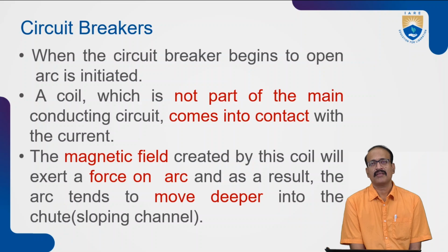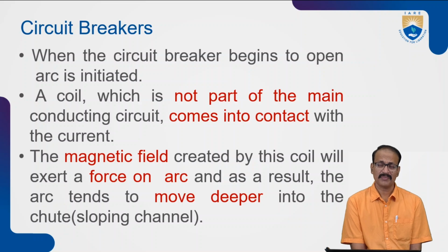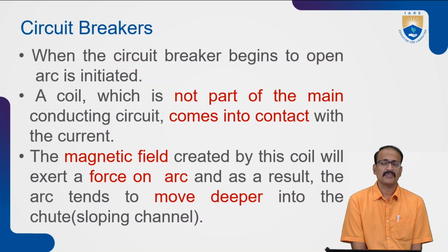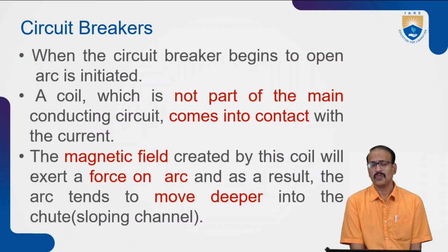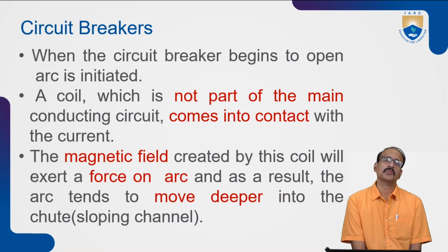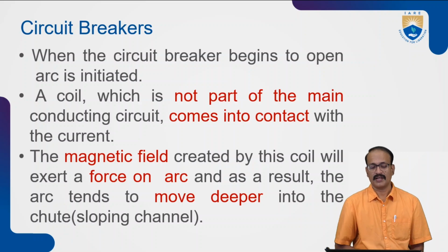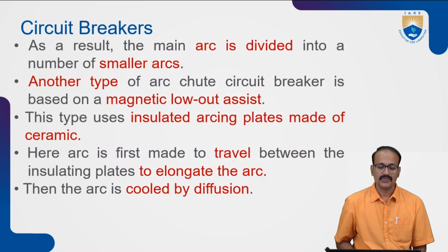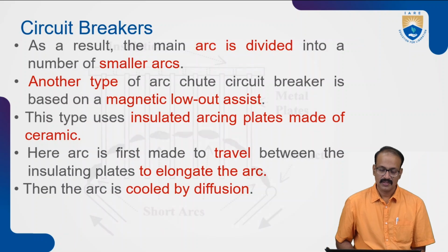These plates divide the arc, and we make the arc flow through this series of plates, hence dividing it into smaller arcs, and it is cooled by diffusion.